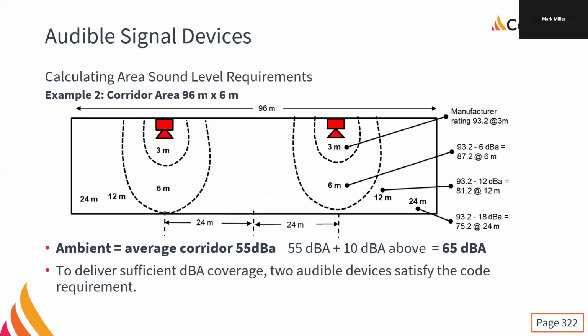And down hallways, sometimes we're going really, really far between devices. Generally speaking, at a 6 meter wide corridor, which is a 20 foot wide corridor, fairly wide, we can go like 48 meters between devices and 24 meters from the end to get adequate coverage.